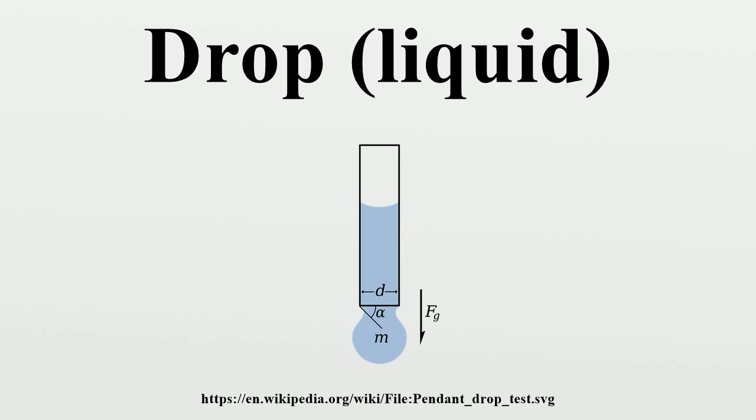The measurement of both adhesion forms can be done with the centrifugal adhesion balance. The CAB uses a combination of centrifugal and gravitational forces to obtain any ratio of lateral and normal forces. For example, it can apply a normal force at zero lateral force for the drop to fly off away from the surface in the normal direction, or it can induce a lateral force at zero normal force.